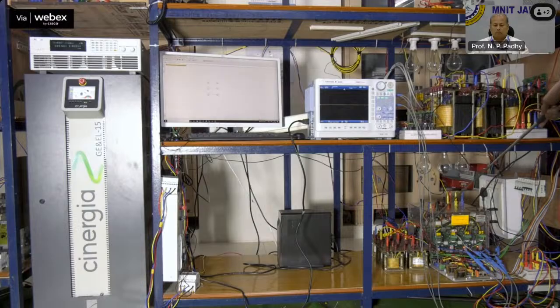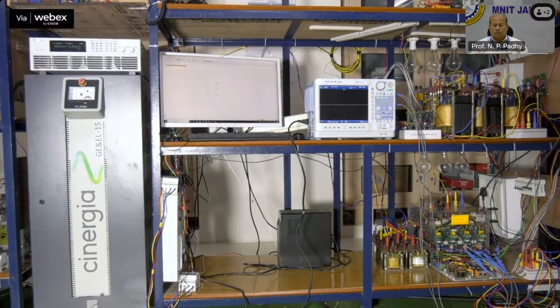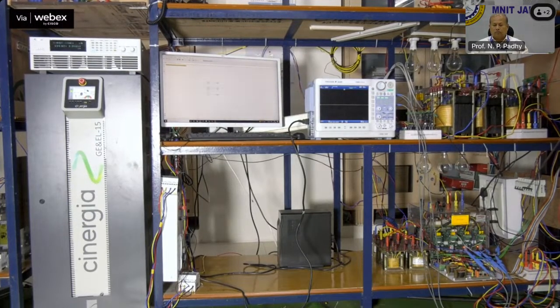For each phase, we have connected 2 such inductor boxes in series to form a total inductance per phase of 6 millihenry. The other ends of the inductors are connected to the point of common coupling, PCC, formed by this MCB. At this MCB connection, bulb loads are connected in a parallel path and they act as a load. The other side of the MCB is connected to the output side of the grid emulator,